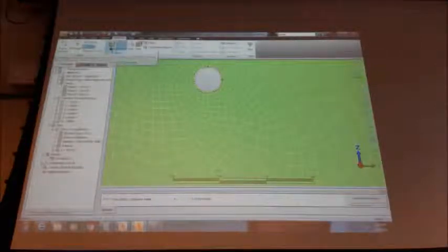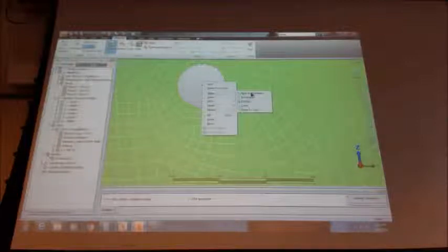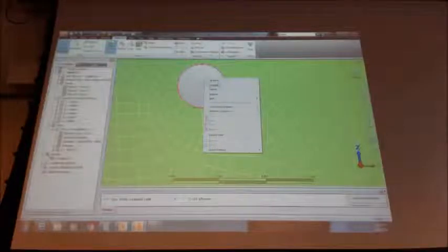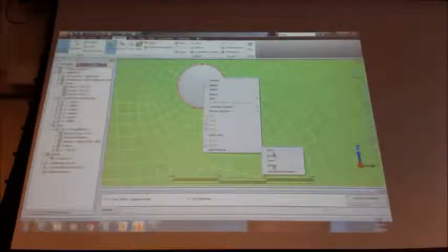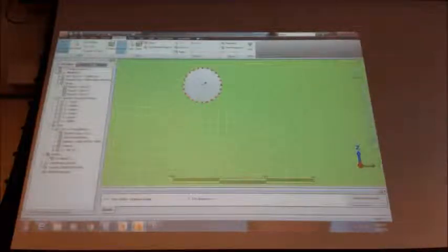The other way to do it is you can select surfaces, come up to the edge, pick the surface, well maybe we can. Oh, because I'm still on, I gotta change my shape. Go back to point. Okay, so now I can pick, you'll see it highlighted the whole circle. If you right click out in the open space and go down to select related and then click vertices, it'll pick all the vertices. So a couple of ways of picking the vertices for a circle when you have lots of nodes defining the edge of your circle.